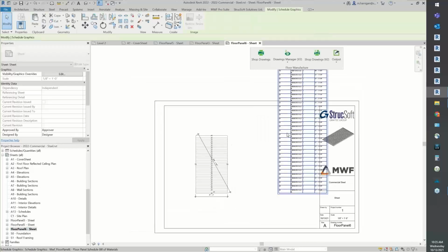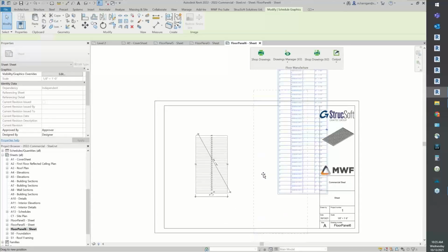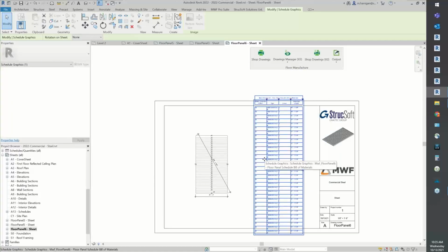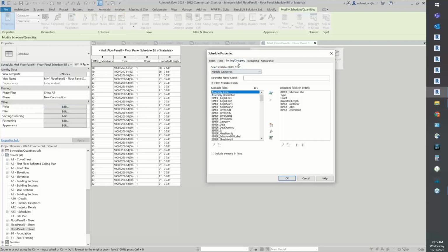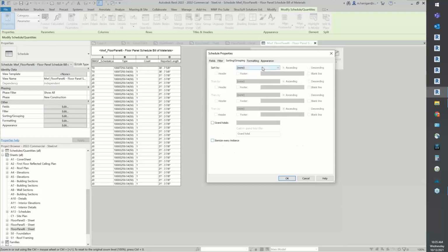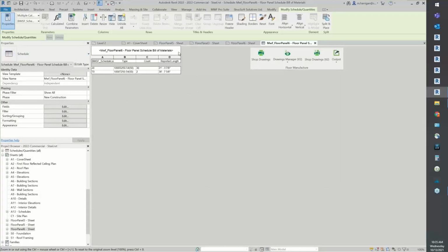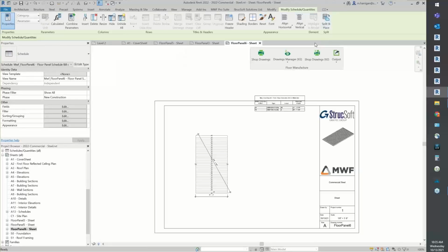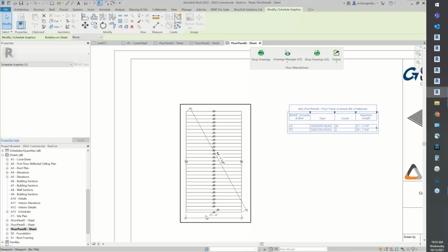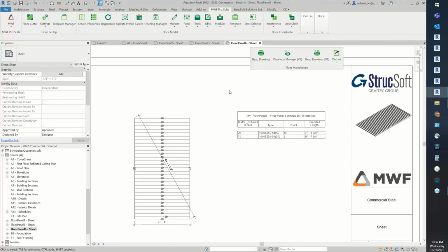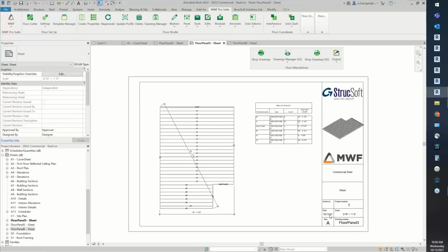And again, for our sheet panel 6, I would do exactly the same thing. Again, the easier method would be just to go into the drawing settings and set that up there so that you don't have to keep going in here and doing that same change, since the drawing settings will give you exactly what you're looking for. This one's a little bit small since it's a very plain panel. Most of the panel numbers are exactly the same. So that's why our bill of material is a little bit smaller compared to the other sheets that we have.